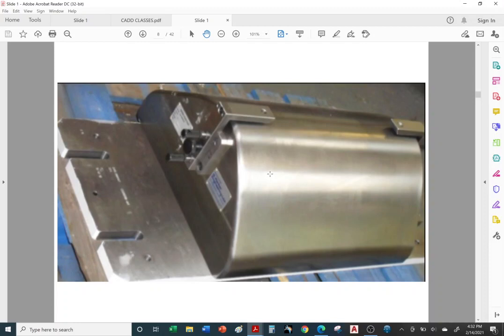So when you take a sheet of aluminum, it's very flimsy, just like a sheet of paper. Sometimes you're dealing with a thickness of about 30 thousandths, or 10 thousandths, again, something the thickness of a credit card or double the thickness of a credit card, but usually around the thickness of a credit card. So these aluminum sheets, in order to form them to the shape of a fuselage or the shape of a wing, especially the leading edge of a wing, you need to take this piece of sheet metal and stretch it and change its shape.